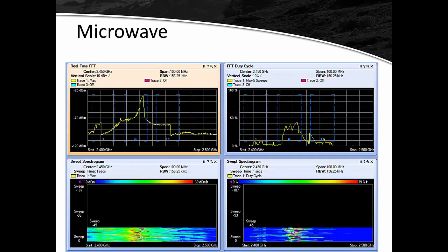Microwave ovens can take out half or even all of 2.4 gigahertz, but thankfully their energy level is very low. So if you get significantly far from the microwave, usually 15 to 20 feet away, in most cases, the energy from it has diminished enough to where it won't cause major problems, but some leaky microwave ovens could cause problems even 30 or 40 feet away, though hopefully that is not the kind of microwave oven you're using in an enterprise environment or even in your home.